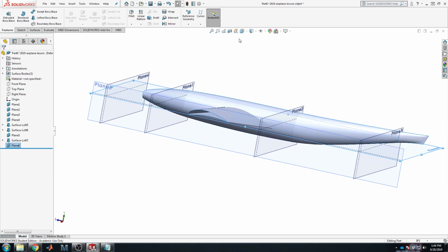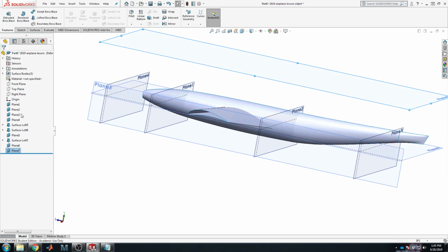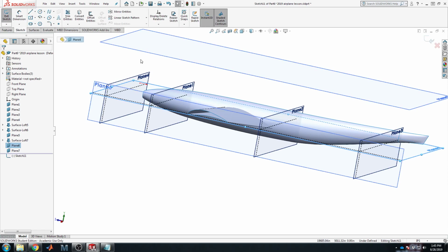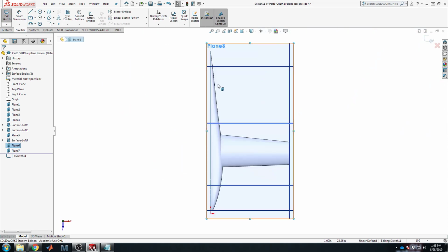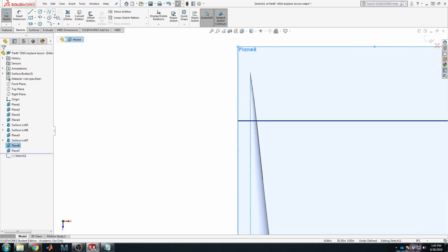Let's make another plane at the top height of the vertical tail. So offsetting it from the previously defined, so that is selected, that's good. Say we wanted a vertical tail that is 5 inches tall. Cool, great, wonderful. Let's go to plane 6, and here you could either bring in half of an NACA asymmetric airfoil, or really